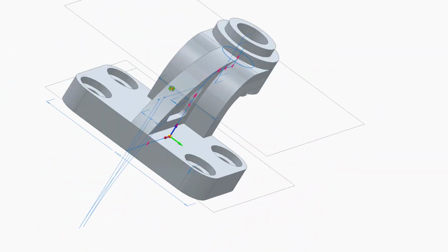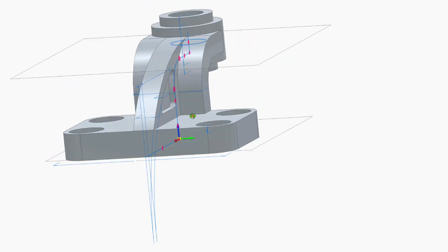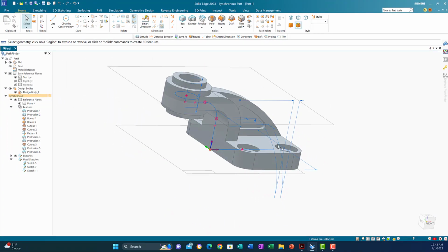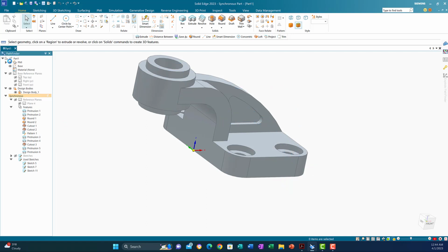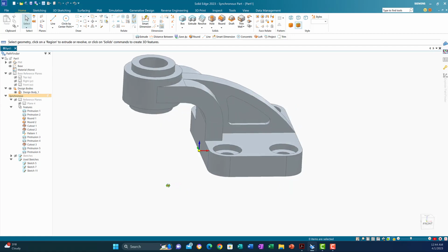And it looks very nice. Okay, I hope that you like this approach. And let me start cleaning this shape here. So what I'm going to do, I'm going to hide the top planes. I'm going to hide the plane I just built. And the sketches, I'm going to hide these sketches. What else do I need? Hide these. Okay, that's it. So this is the shape.